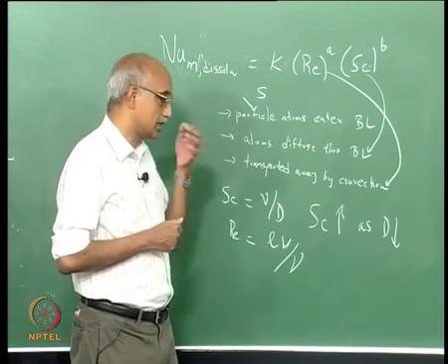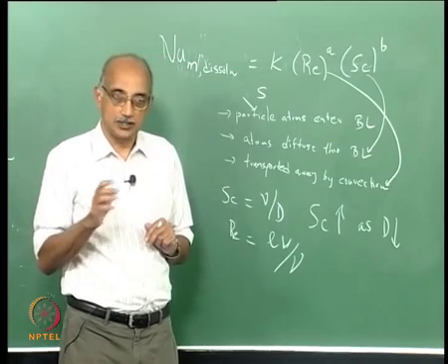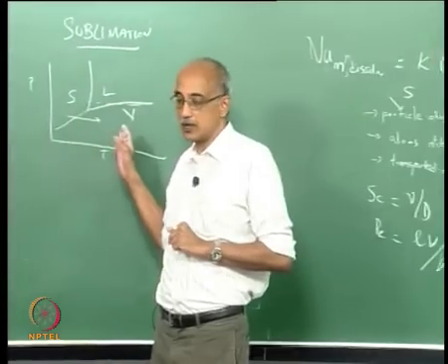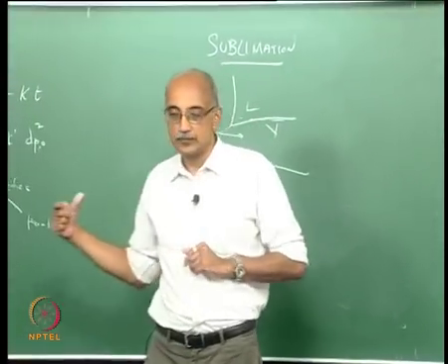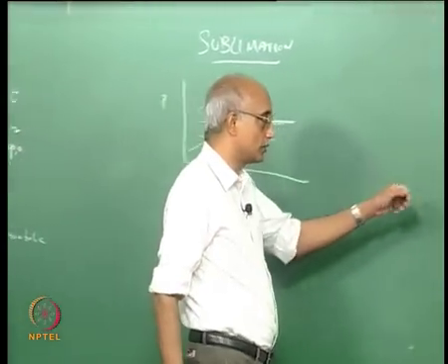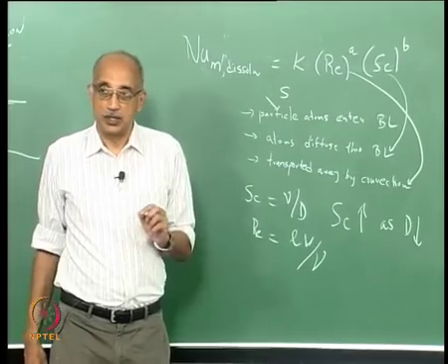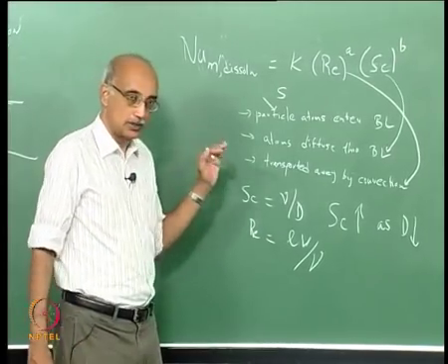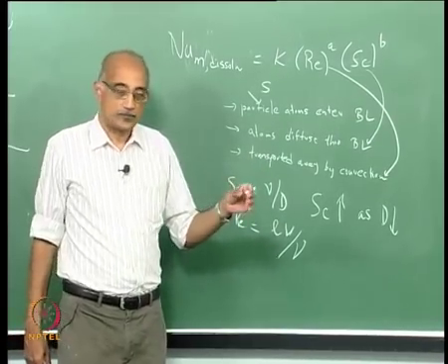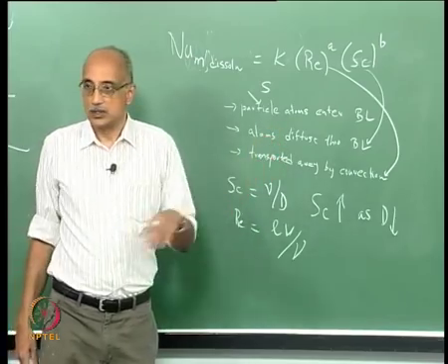Typically this step is the critical step in sublimation, because unless the thermodynamic conditions are favorable, I mean it starts with the phase diagram. If you happen to be in a temperature-pressure regime where sublimation is not possible, it does not matter if your transport conditions are designed to be favorable to sublimation. So, unlike dissolution, where as long as a particle is soluble in a liquid, it never becomes the rate limiting step, and these will become the rate limiting steps.